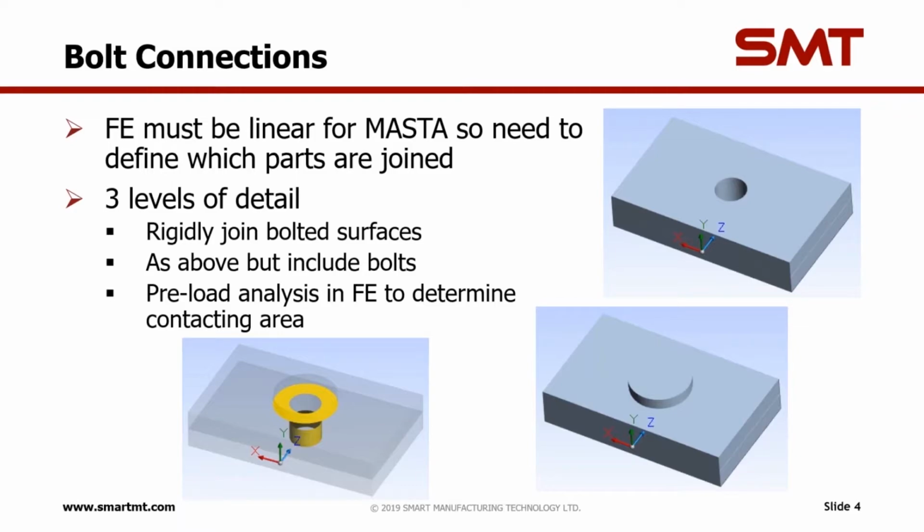The first thing to note is that in MASTA we don't have any support for applying bolt preloads, for example, or doing contact analysis. So what you bring in must be linear. There's three different levels of detail we can go into.